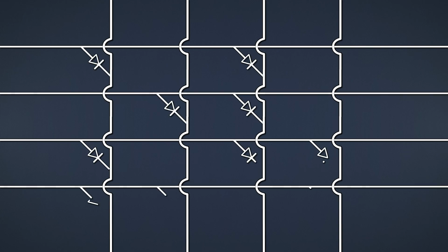Let's start with a grid of word lines and bit lines and build some ROM using diodes. Remember, diodes allow electricity to flow through one direction, but not the other. With diodes in our grid of cells, if we activate one of our word lines, watch what happens. Wherever there's a diode, current will flow from the word line into the bit line. In other words, at each diode we are going to find a 1.